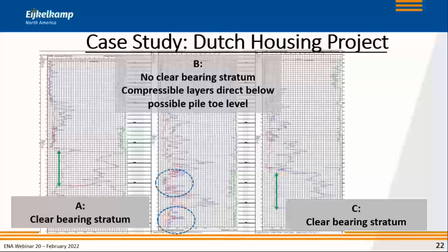Secondly, we need to think about the type of pile that you're selecting. If you don't do an extensive soil investigation, if you just trust a preliminary soil investigation and hope for the best, maybe concrete piles are not the best solution. Maybe that's something you need to take into your risk evaluation. Does it make sense to use concrete piles? Because what happens if I come up with more site variability than I expect? How am I going to address it in my pile driving?